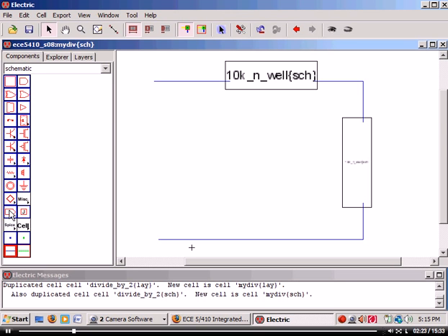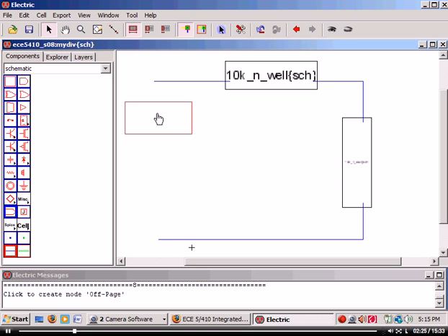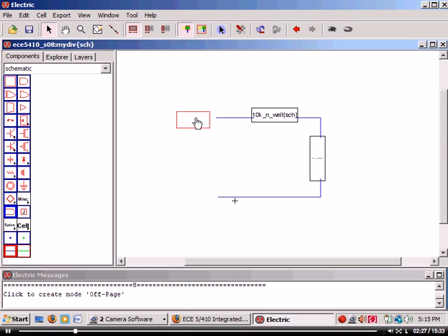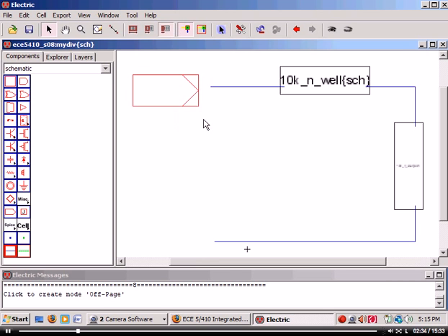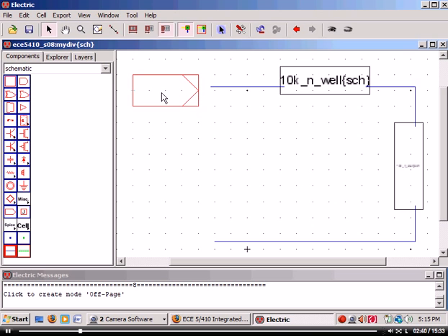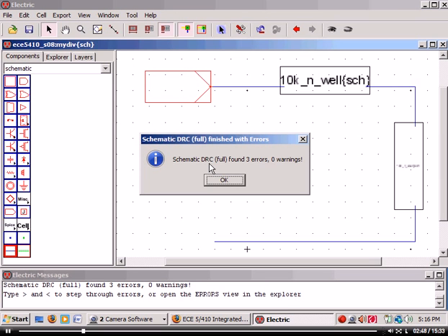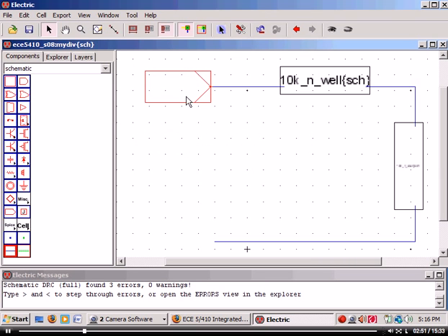The reason I'm doing this is this tells me, press X, what nodes are connected where. So put it on quarter step again. And I can put the grid on if I want. Now I've got 2 ports on this off-page connector. It doesn't matter which one I use to connect up. Now of course if I do this, it's not connected. But if I hit F5, it'll tell me it's not connected. Okay, so what I'm going to do instead, first off, I'm going to show these.